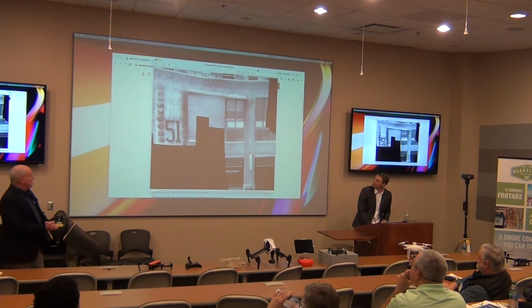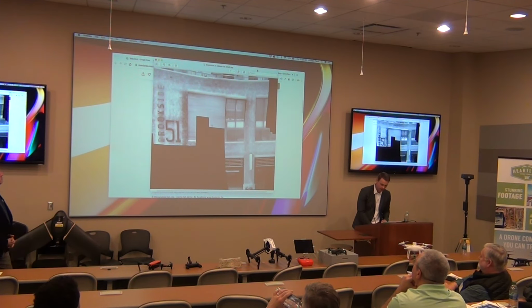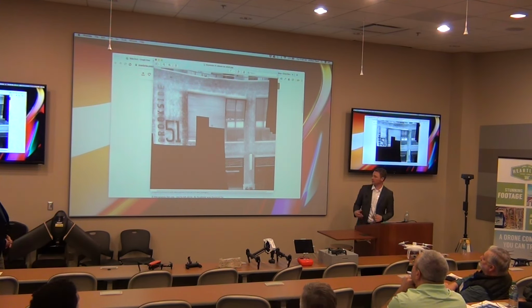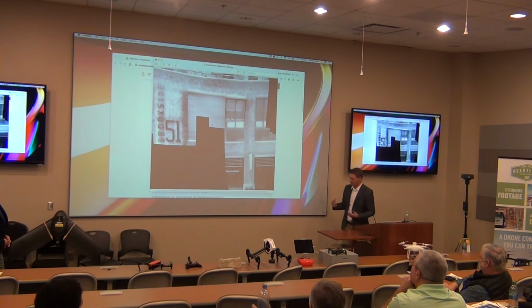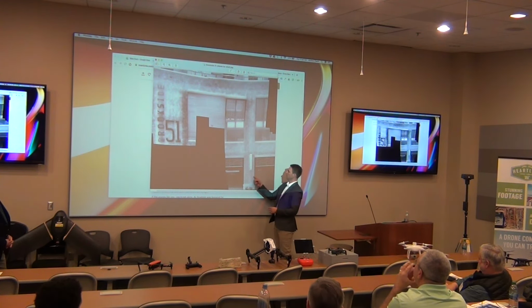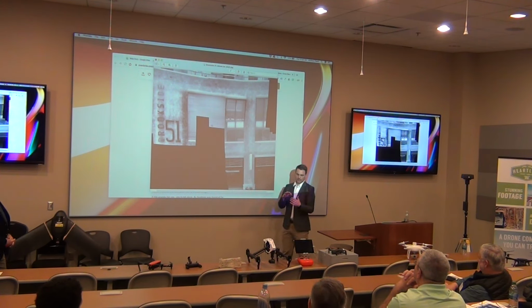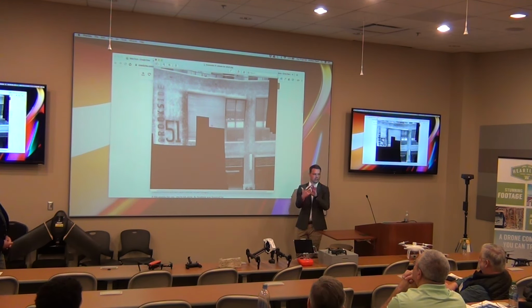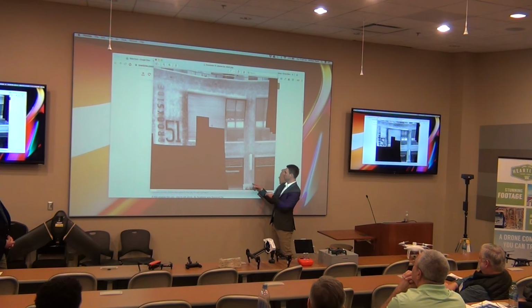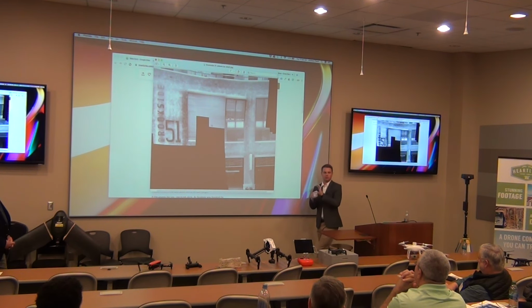Here's another example of what that looks like. This is stitched together. So basically, the heat signature that we can come away with, in this case, the darker shaded areas indicate that there is a cooler background behind it, that there is a void, right, that there's cool air. The bright white hot areas indicate that the back of the stone is fully buttered with mortar, because then it turns into a hot plate, right?